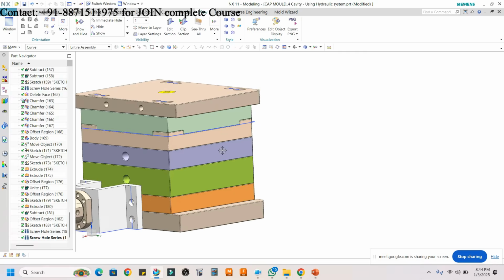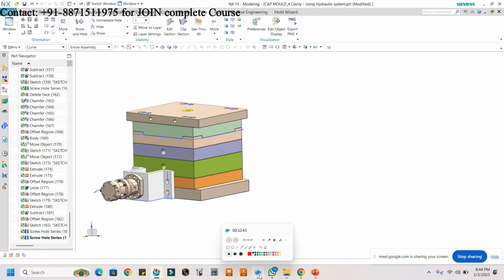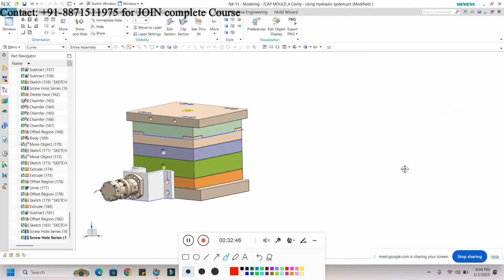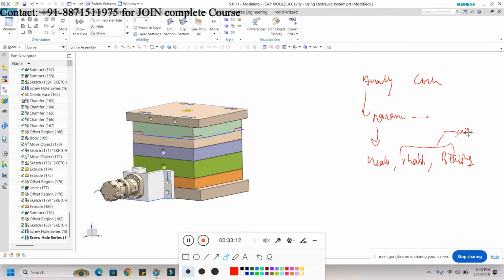As I told you, what I have mentioned about the gear: first of all, analyze the component. Find the parameters of the component and the dimensions. Depending upon those dimensions, we have to select the gears, module, shaft diameter, and bearings, with the manufacturing aspect.